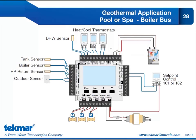So if I use the Tekmar thermostat 553 for this radiant heat cool application, then I have a built-in humidity sensor that I need to make sure I'm doing dew point reset. If I only wanted to do radiant heating and I wasn't concerned about radiant cooling, I could do so. I would just choose a heat-only thermostat.